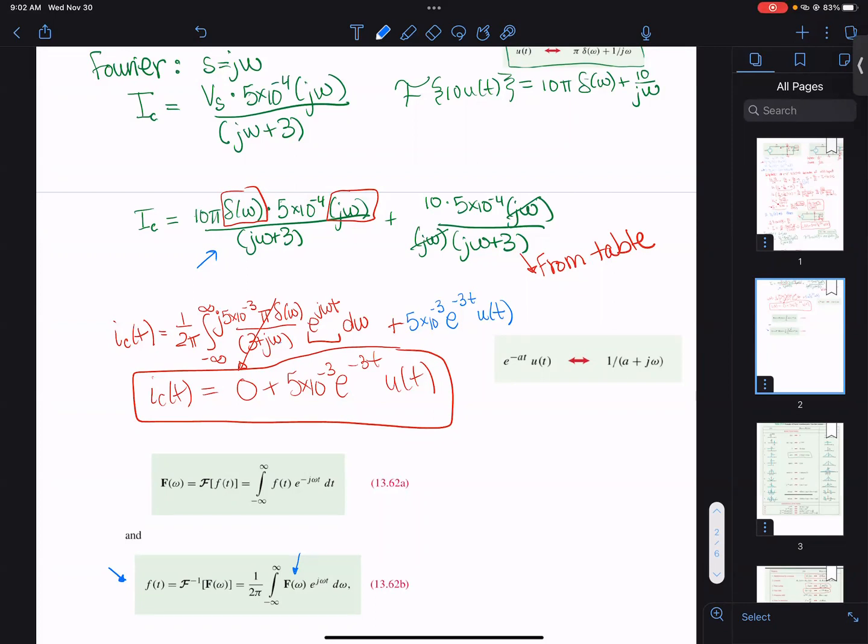So essentially, the first thing is you did the integration on that part of some function because there wasn't anything in the table that translated it. Then the next step is, because there's a delta omega in that integral, when you integrate it from negative infinity to infinity it goes to 0. Is that a safe understanding? Yep, when it's this form, when you have delta omega times e to the j omega t over a plus j omega, it's that combination that gives you the 0.